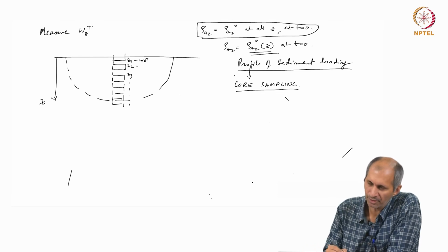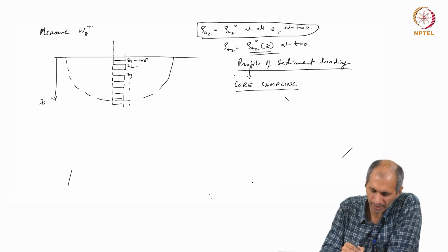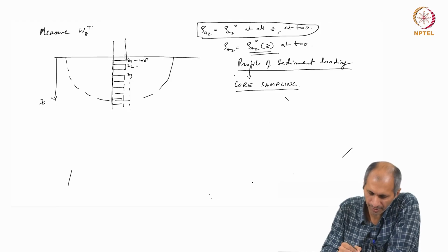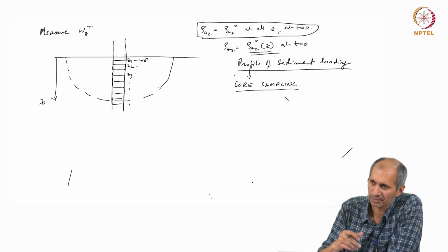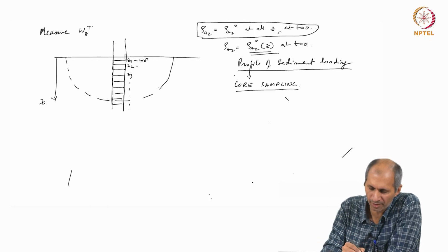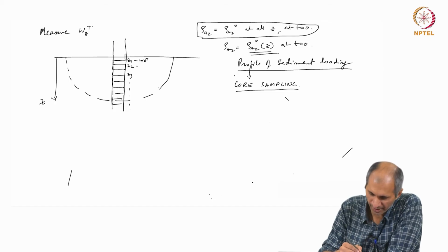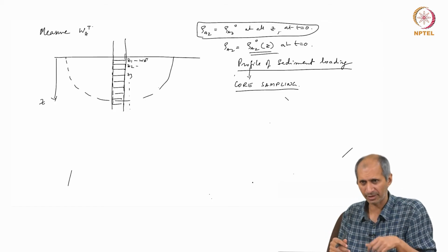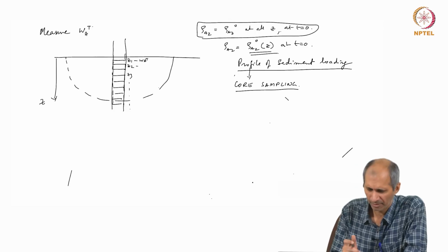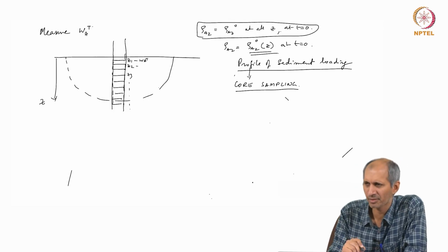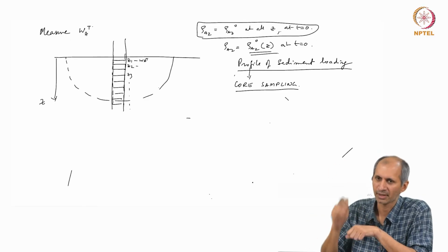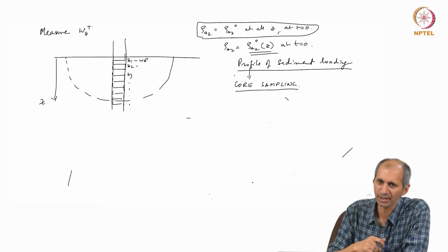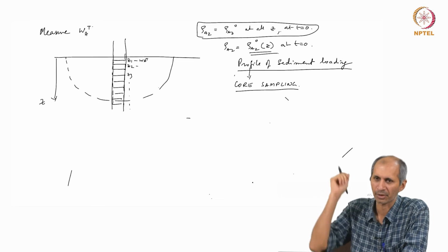Usually in core sampling we put a tube into the sediment and we pull it out. It is a very tricky process. The moment you put a tube inside, it is sometimes difficult for the tube to go inside. But for sediments it is reasonably wet, so it is fine. For soils, it will not go, you have to hammer it in, then loosen it and pull it out.